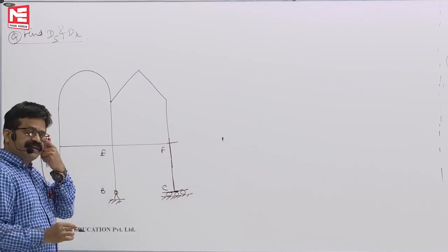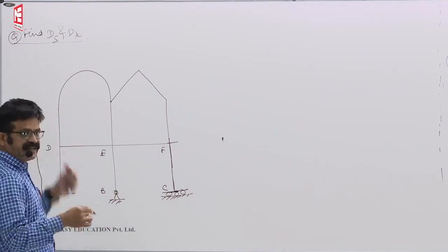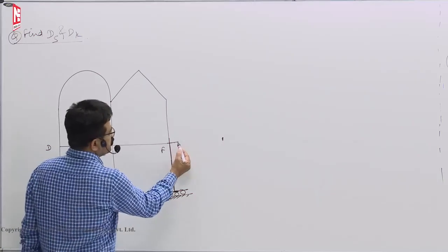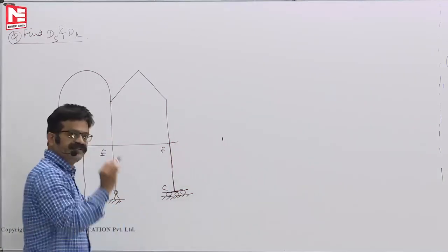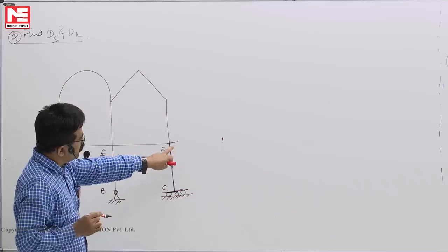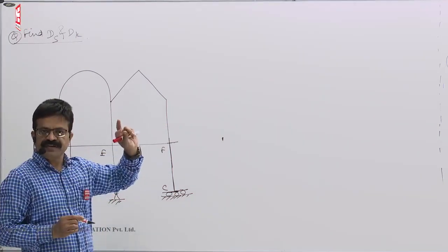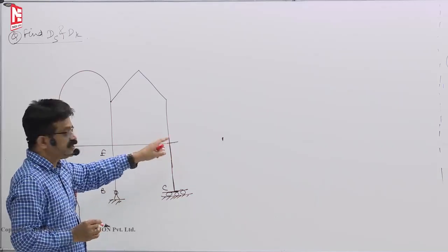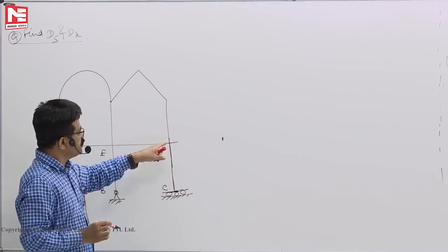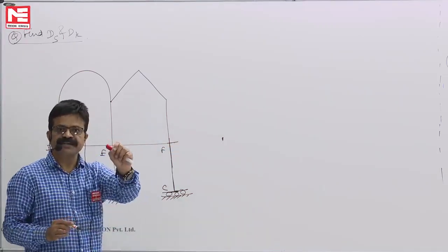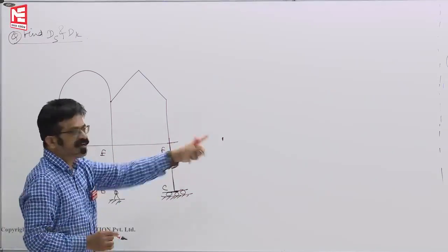When you are calculating ds or dk, the kinematic indeterminacy, this also you have to consider as a joint. A free end is a joint. We should not think that accidentally he extended the line. Let us ignore, we should not think that way, because once a line is shown, however small it is, if it extended beyond, that is like a cantilever.